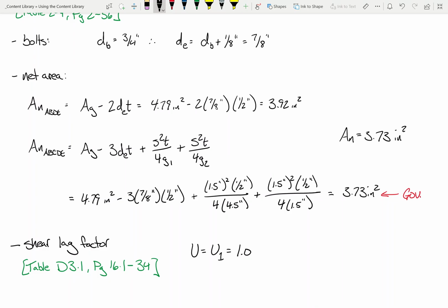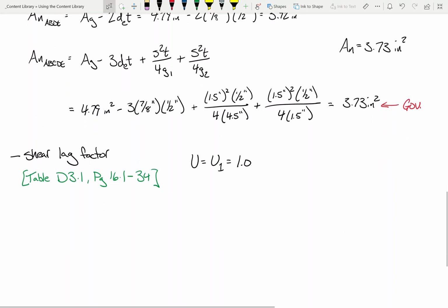Now, I'm sure there's some engineer out there who will probably say, yeah, but maybe we should apply case A because it is a single angle with 3 fasteners per line or what have you. We can have that debate, but again, all of the cross-sectional elements are connected. Okay. Well, case 1 would still govern anyway because it's larger. Yep. All right.